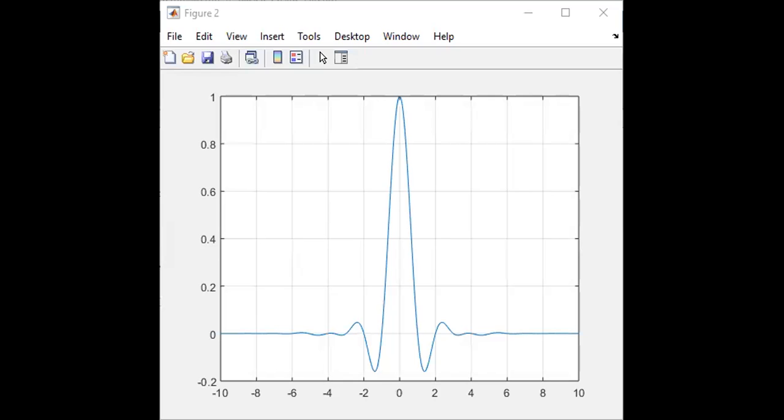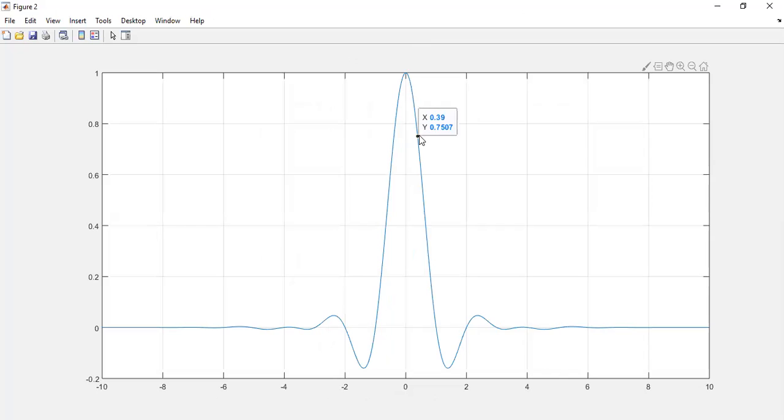So, that being said, the main concern over here is what happens if I pass one raised cosine filtered system through the same one again? That is what happens when you do multiplication of two transfer functions, or convolution in this case of two time domain variables. So what we have done over here is taken the convolution of the roll off factor r equal to 0.4 wave.